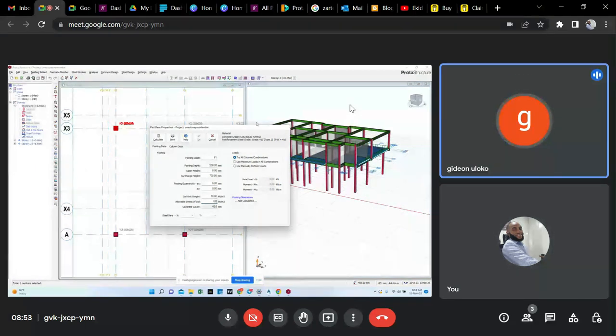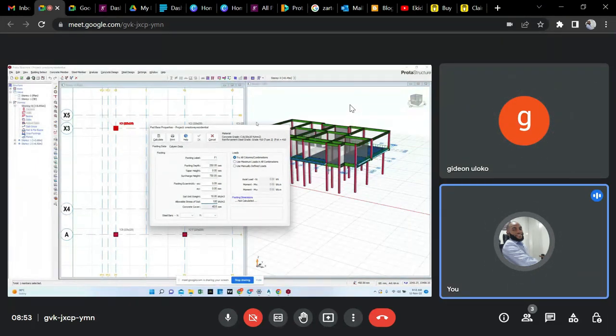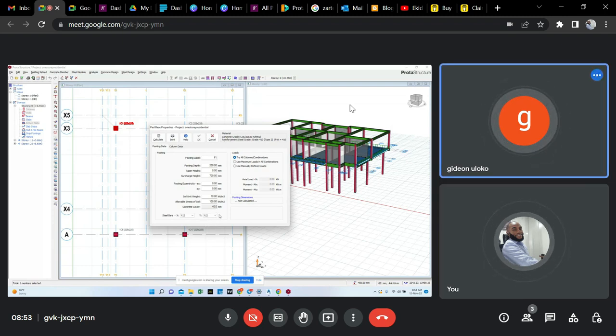Then now choose your steel bar sizes, on X and on Y. Click on that arrow and choose 12. Since this is a one-story small building, you choose 12. But had it been a two-story building, you would choose 16. Okay, now click on calculate.